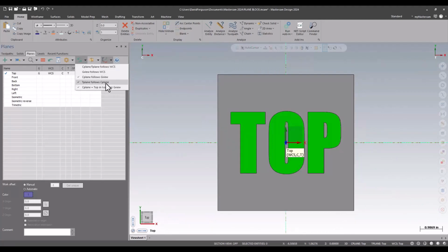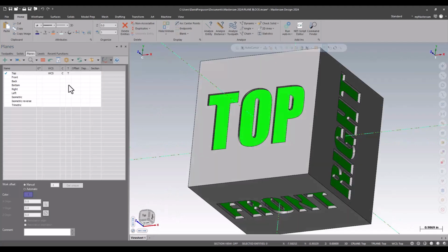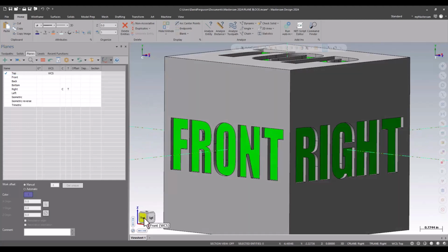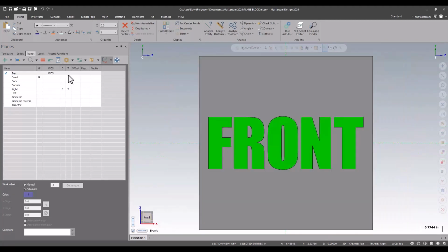Now, these views are changing the graphics view, so if your follow rules are set, if you execute the right view command on the GView Cube, the construction plane and the tool plane follow along. So if we turn off those follow rules, this isn't new functionality, but if I turn off those follow rules, now those will stay put and only the graphics view is being adjusted.